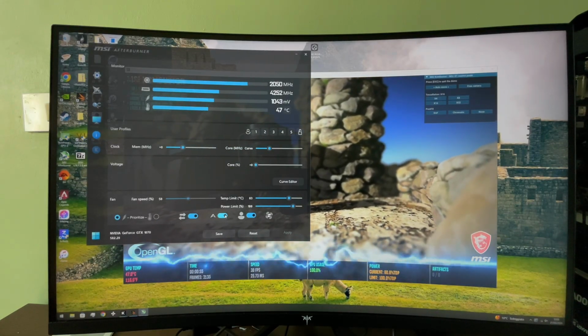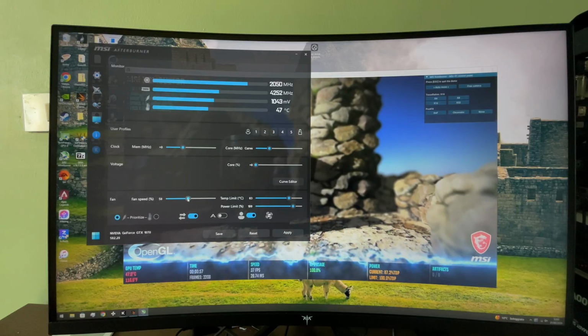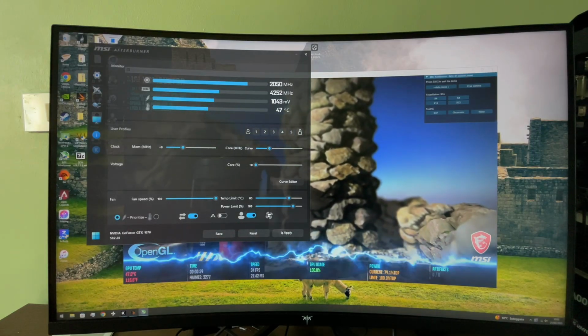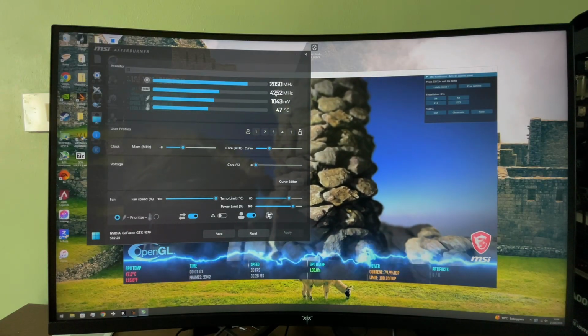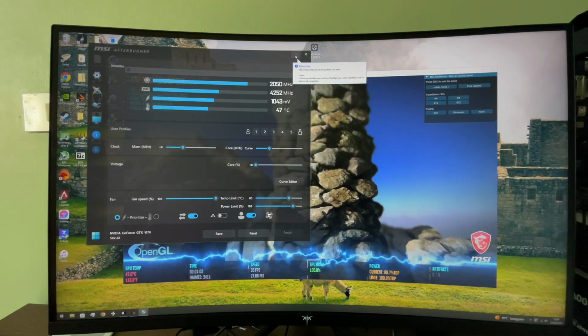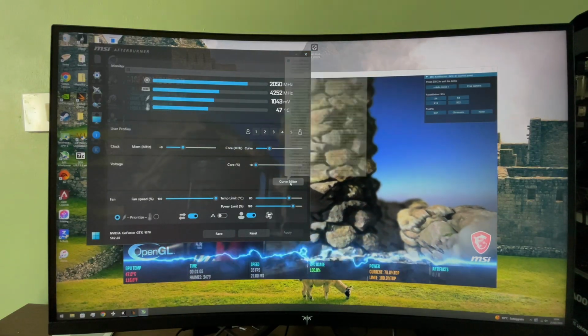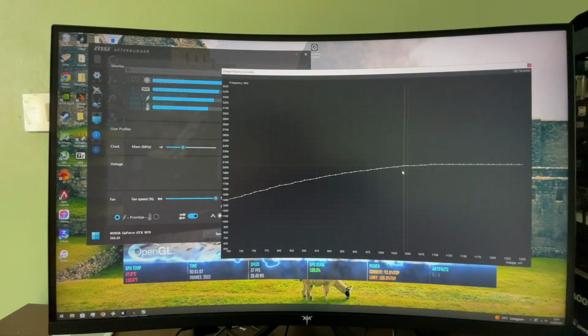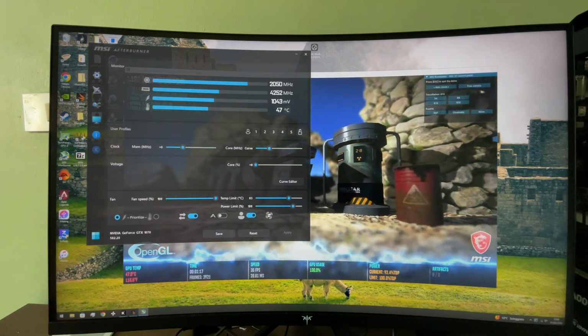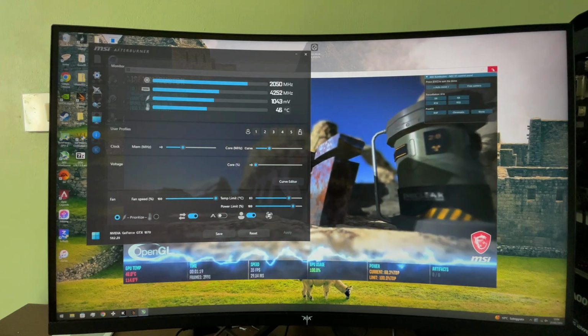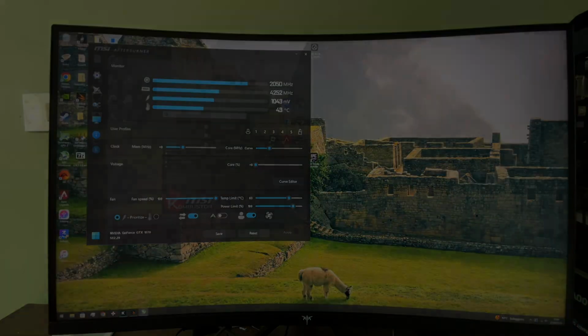I will now increase my fan speed to maximum so I can decrease the core temps. Seeing as how we haven't experienced any artifacting or crashing, we can repeat the process. You want to keep repeating this process until you experience any crashing or artifacting, which is when you'll want to turn down your undervolt. If you want to be more certain of the stability of your undervolt, you can run the artifact scanner in MSI Kombustor.